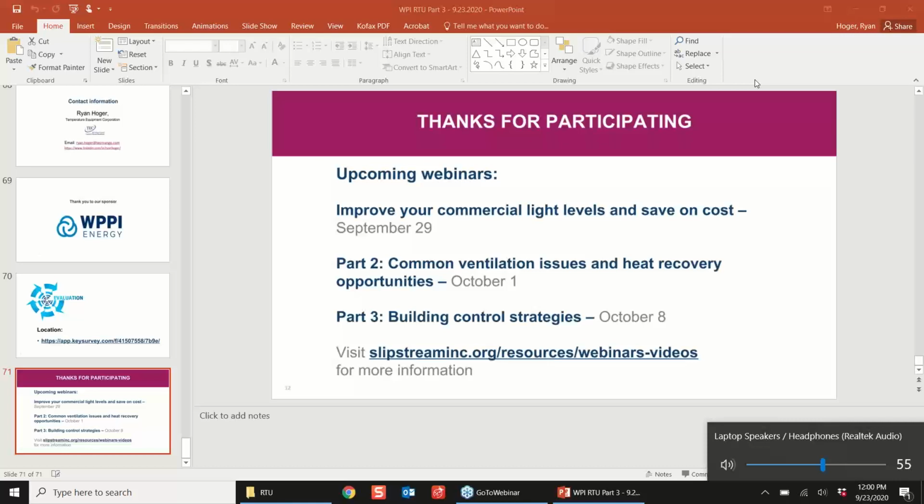Yes, I can hear you. Okay, sweet. All right, so just for argument's sake, I didn't light this unit up very well yet, but the other ones I did. I'm only going to show you this one briefly. Your typical rooftop unit is going to have a belt-driven fan like this. On the left-hand side there is the motor. This little guy here is my motor. This is my fan assembly. Both of them have a pulley on it, and there's a belt that connects the two. This is the most common scenario.